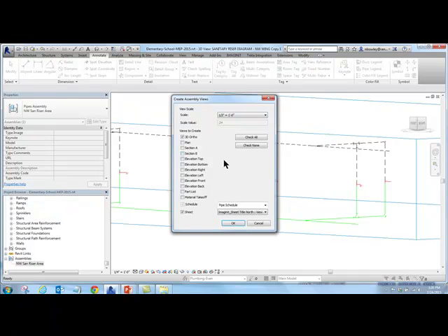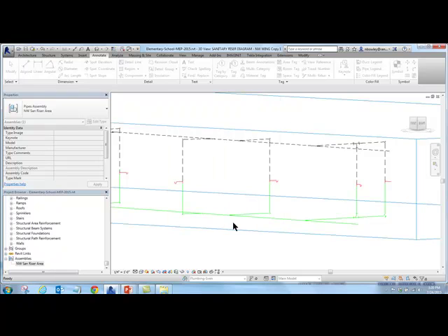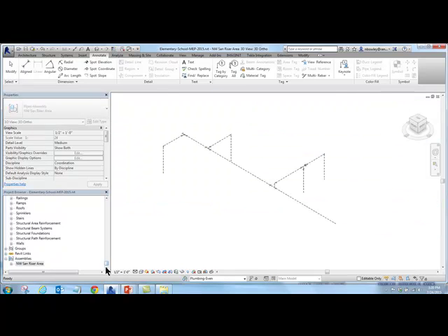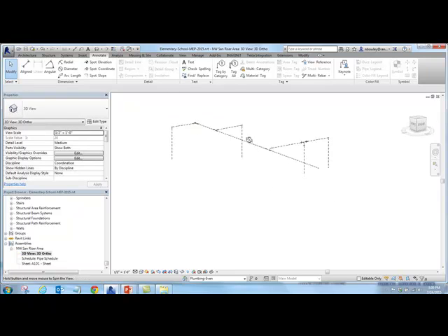This is probably a new tool for a lot of people, but I'm glad you brought it up. I can create plan views of this, 3D orthographics and things like that. I can even create schedules, although I'll often just create schedules for these assemblies and then filter them based on assembly name. But you can create a 3D view out of it here, hit OK. That's the only view I was creating out of it in this case. And then there's my 3D orthographic out of it pretty quick. So that's a good alternative.